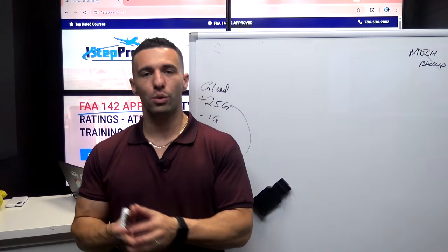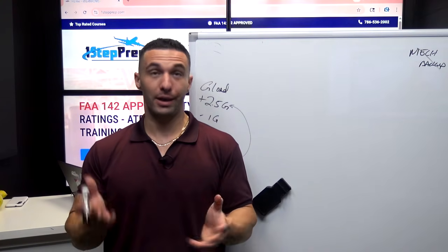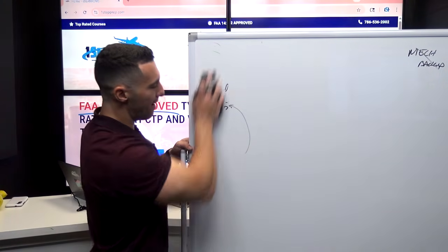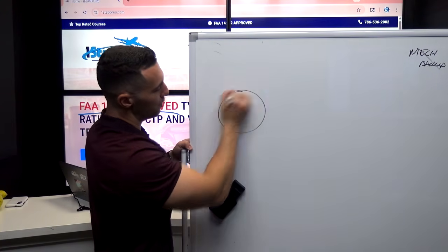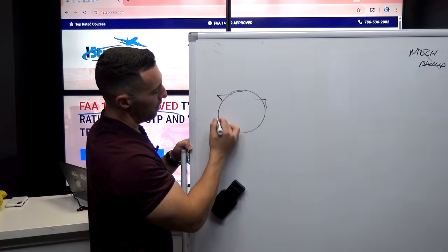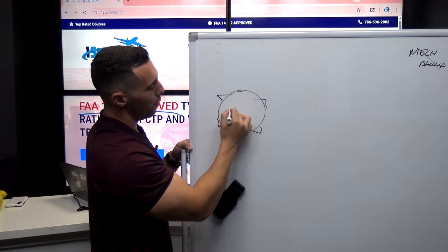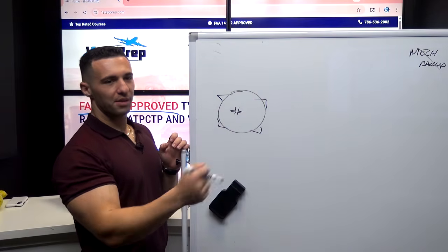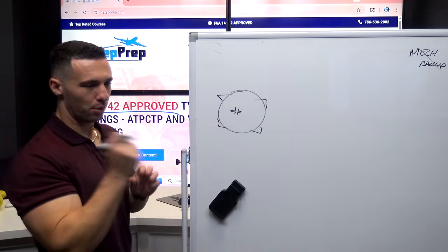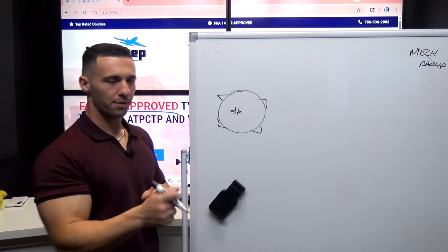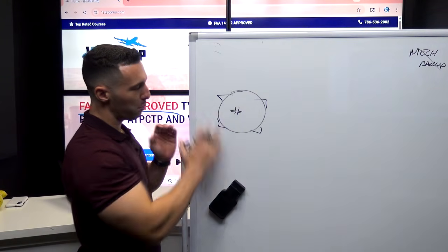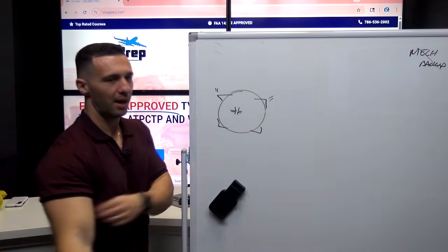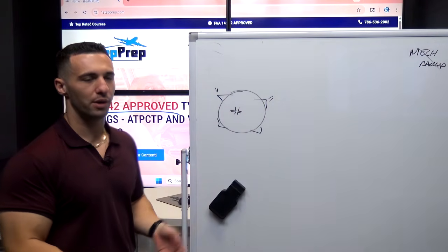You will know that you are there dominantly by A, you're obviously on the ground, but B, the attitude indicator will have right angles like this. And those right angles, along with the crosshair, are the limits of the side stick deflection: full aft, full up, down, neutral, full left, right, neutral. When you see that presentation on the attitude indicator, you'll also see the green equal signs here, and of course you're going to have your engines running and you're on the ground. You know you're in ground mode.